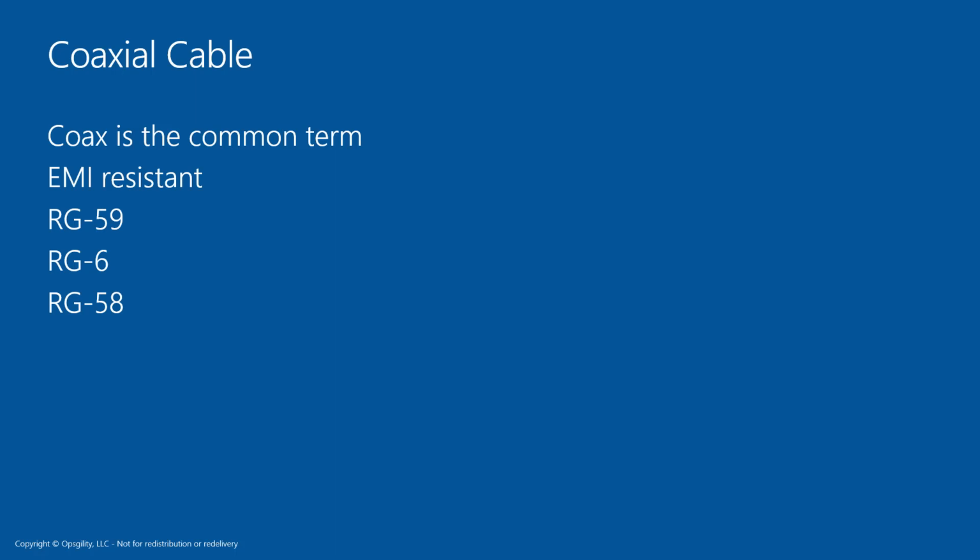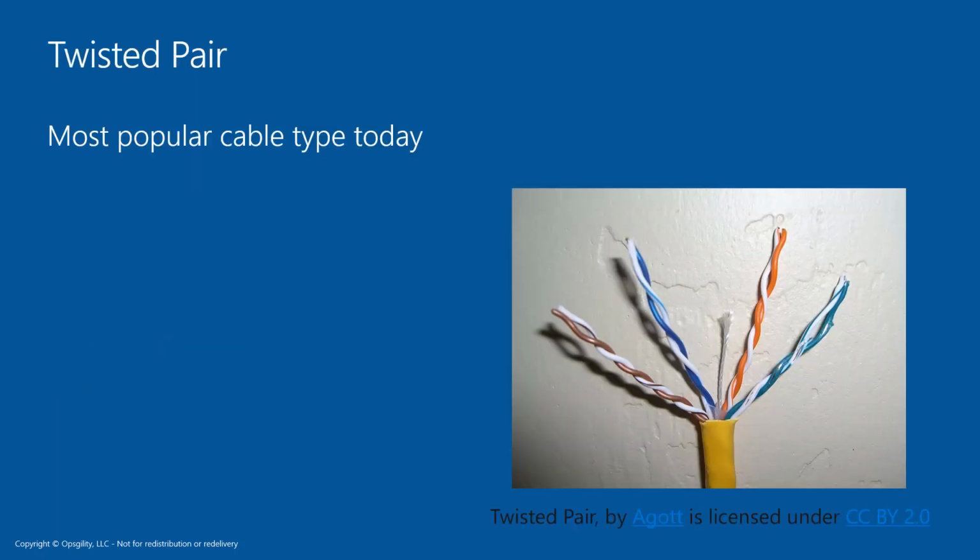It refers to the amount of resistance compared to the flow of electrical energy. A 50 ohm cable will give us a better result than a 75 ohm cable. The RG58 gives us the 50 ohms and the other two cables give us the 75 ohm. However, most installers are going to use the RG59 and the RG6 because they're already installed in network offices. The BNC connector was typically used for connecting network interface cards, and the F connector is now used for cable TV connections.